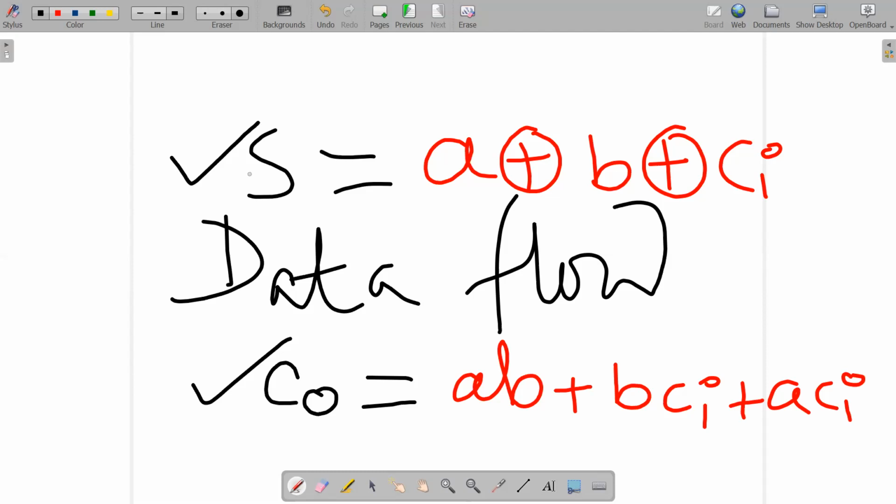You can just call that single bit adder function, that is called a module. In Verilog, we shall use the term module, not function. So you can call the module of the single bit adder and then just connect it in a particular way, so that the 4-bit adder will be designed. Basically, this programming language supports design portability.